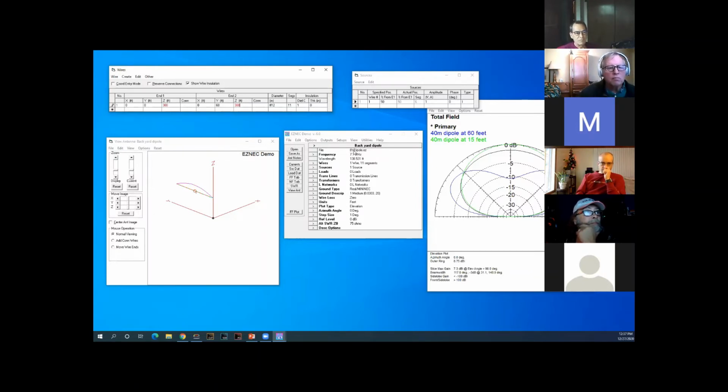For example, if all you want to do is stateside rag chew, well, maybe you want to optimize your antenna for the elevation maybe between 40 and 30 degrees. If, however, you want to talk to Bangladesh every morning, you need to optimize your antenna for these elevations down here. So a lower takeoff angle to get that skip further. Exactly.